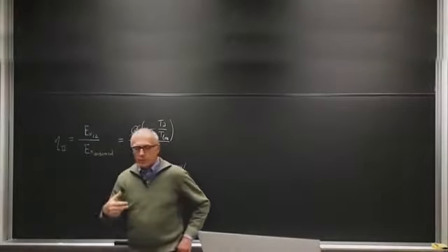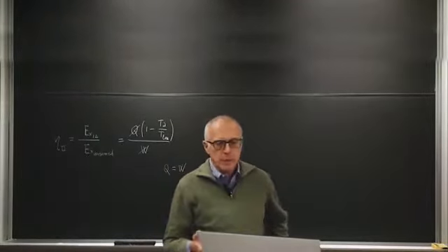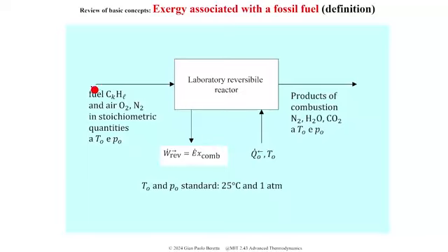So how do you compute exergy for a fuel? The idea is the following. You take your fuel at environmental conditions, and you mix it or keep it separate with just sufficient air, the stoichiometric amount of air that is needed to oxidize that fuel.